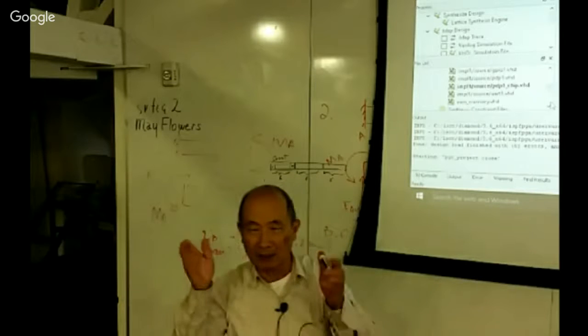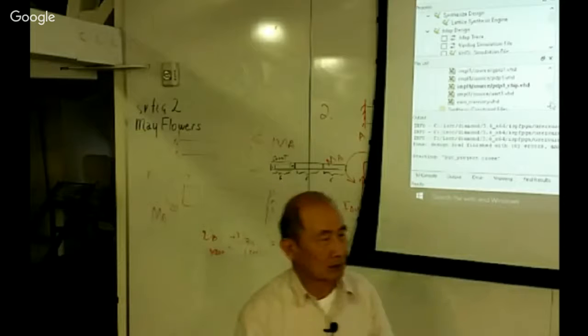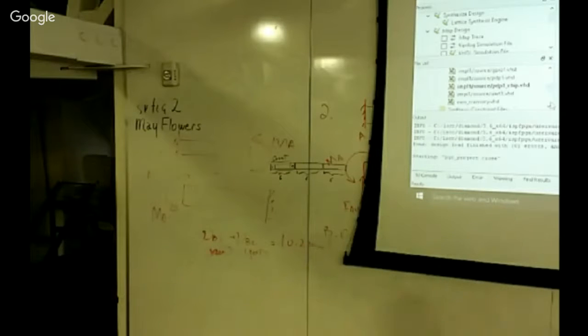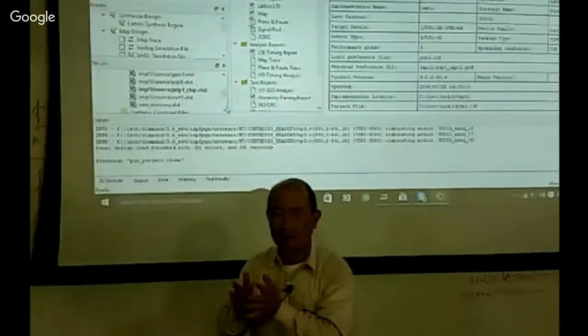So my decision was that I would only allow one level of indirection. Only when you are executing an instruction, and the indirection bit in that instruction is 1, would I fetch the address and then get the data in the next cycle.